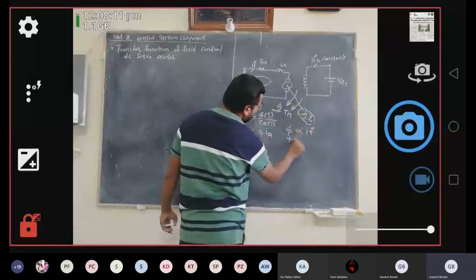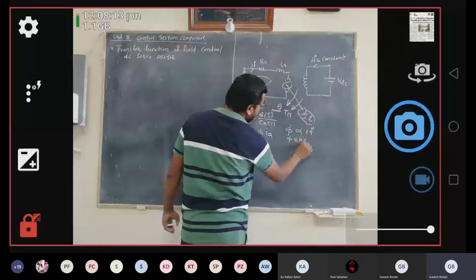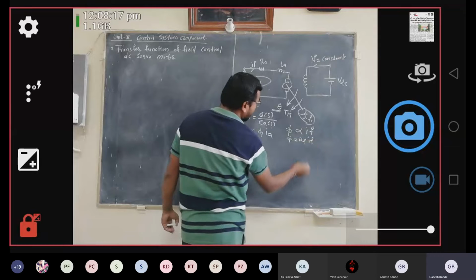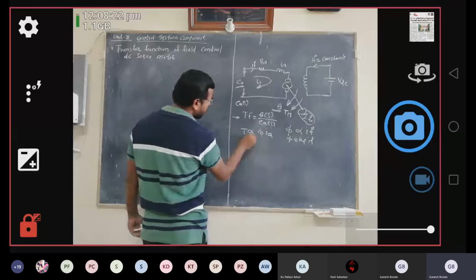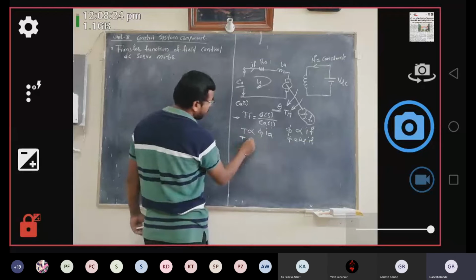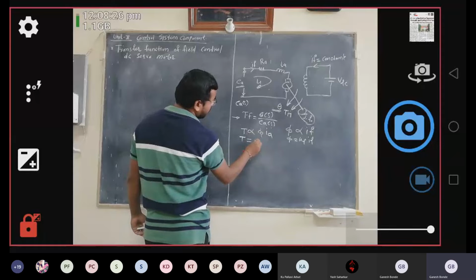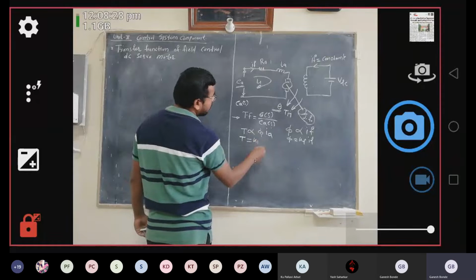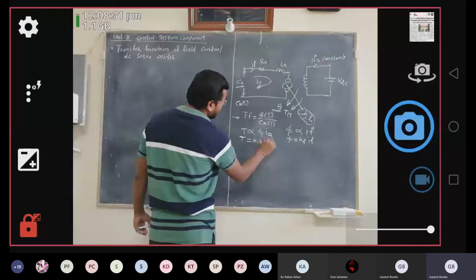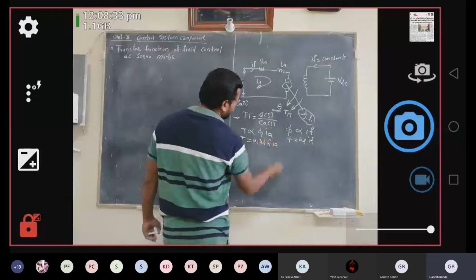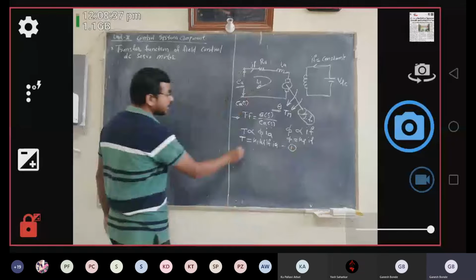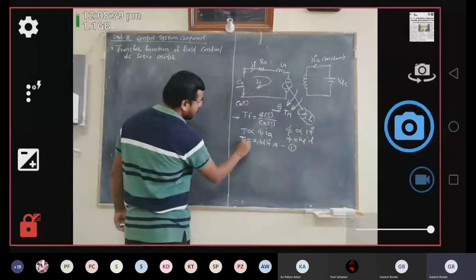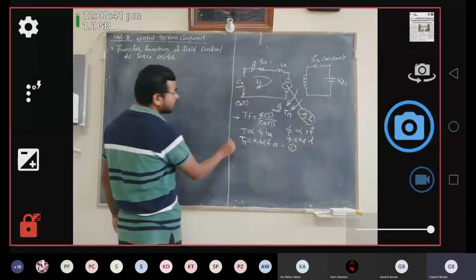So this proportionality constant we have defined by KF times IF. Okay, so substitute this value here. Again, this proportionality we have defined by another constant, so take another constant K1. So it could be K1 KF IF into IA. So this will be given equation number 1. Okay, so this is your torque Tm. Okay, so this is the first step.